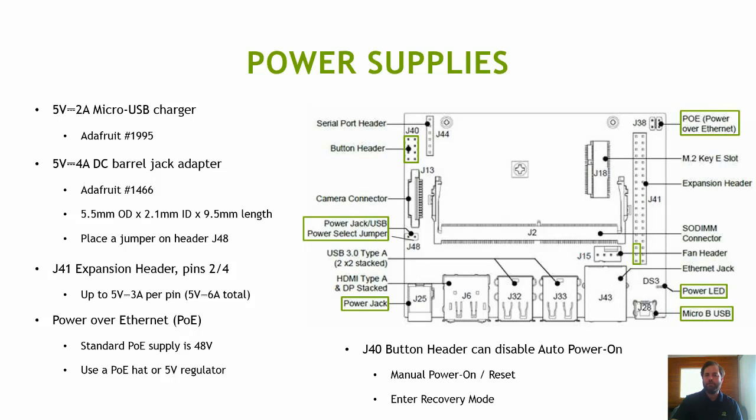It's important to use a high-quality power supply with the Nano that's capable of delivering a consistent 5 volts that won't dip to under 4.75 volts under load. Many typical USB phone chargers aren't designed to deliver this kind of consistent power source, as that isn't what your cell phone really needs, and also these cables that they use can have additional voltage droop. The board may boot up with some of these chargers, but when you plug in more peripherals or go to run something more demanding, the board may brown out and shut off.